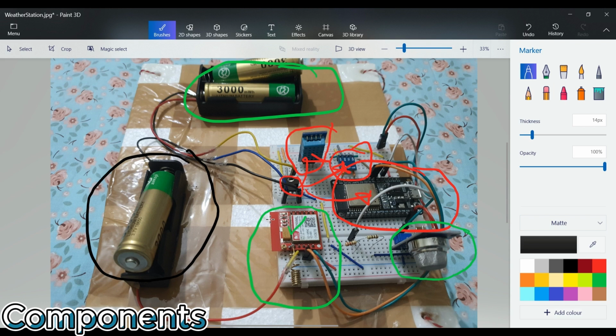And you can't use any kind of jumper wires to supply the power to the SIM800L GSM module, for junction capacitance issues. So the 4.2 volts that I've supplied to the SIM800L GSM module, I have supplied directly without using any jumper cables, because the tops of the jumper cables are clamped using mechanical junctions. There are no solder rings on these caps of the jumper wires. So it eventually generates junction capacitance or disruption or discontinuity. A little bit of discontinuity, might be in milliampere or microampere range, eventually hinders the constant or stable power supply to the SIM800L GSM module.